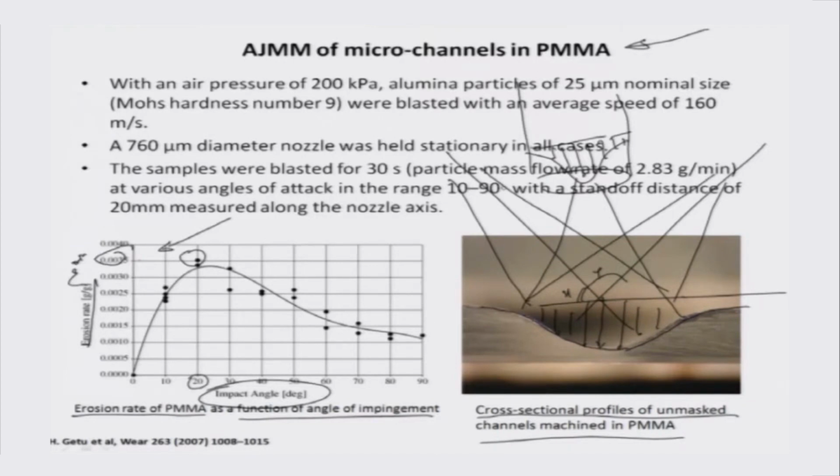This gives a basis which really talks about standoff distances of the nozzle as measured from this plane surface right about here. So, probably around this 20 degree range, the standoff distance is the optimum best. If you may recall, there was a relationship that we derived before in terms of the nozzle tip distance, and we said that the machining rate increases, then plateaus off and falls down as far as the variation of MRR is concerned with the NTD.